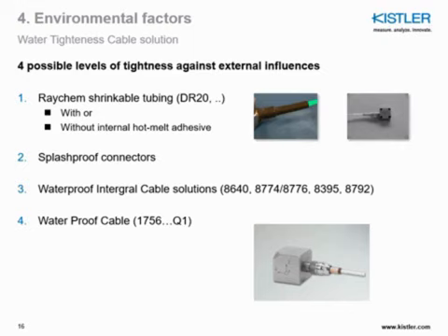And the fourth option is some kind of waterproofed cable. So once again, in that case, it's not an integral cable anymore, such as example 3. It's a separate detachable cable, and there too, if you want to use it underwater for a certain duration in time, you need a specification and a qualification that shows that this solution has been tested under pressure and had a certain level, such as 10 bar, 14 bars for 3 days or so.